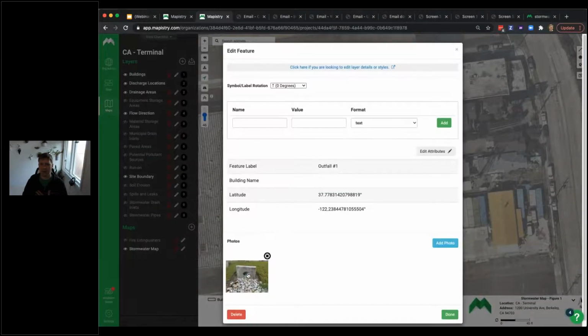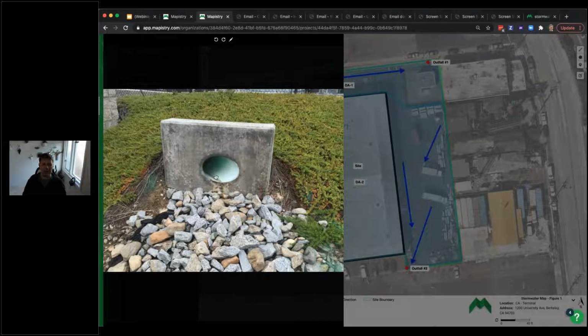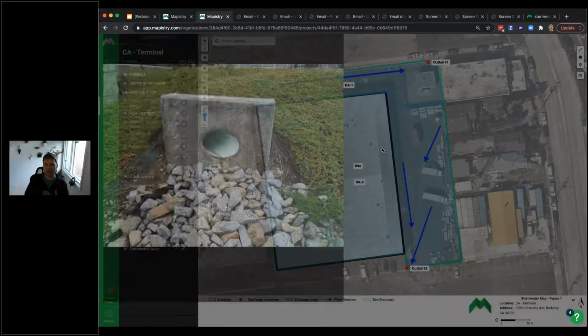I can click on that and then I can see, okay, I am supposed to collect a sample right there. And some folks will even put an arrow and say, collect it in this spot, because you don't want somebody going out and dragging the sample container through the dirt swale and filling it with sediment, which blows out your TSS numbers. You want to have a really good representative sample. So embedding photos in maps can really help communicate that, especially if you have non-environmental personnel doing it.